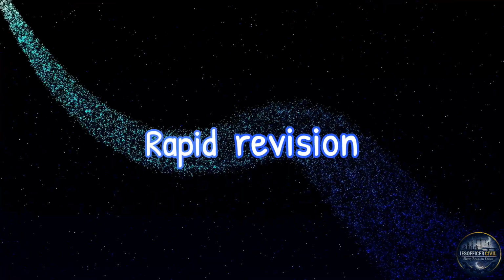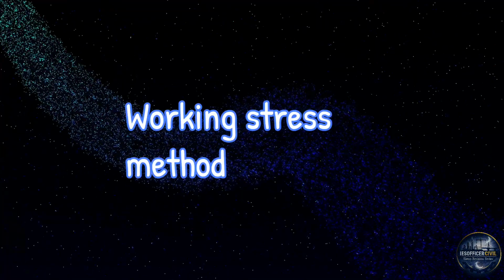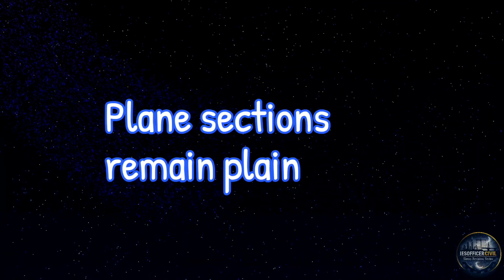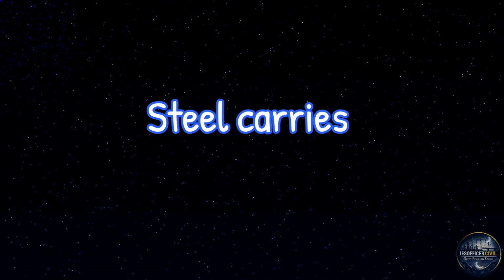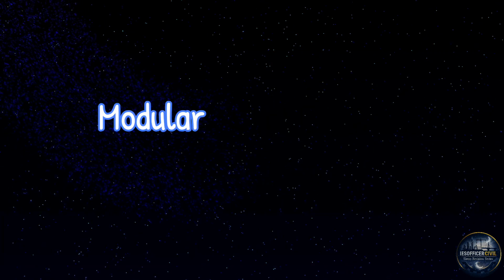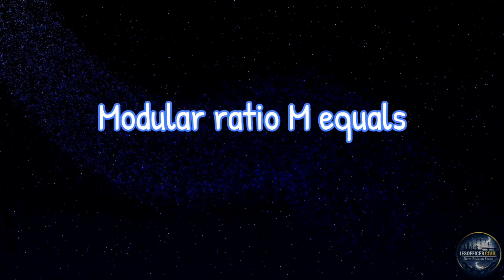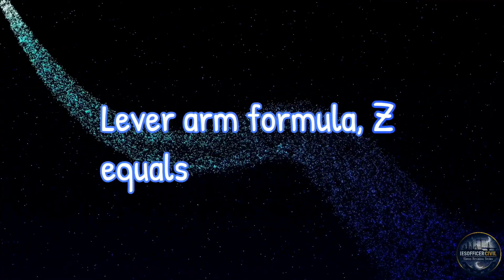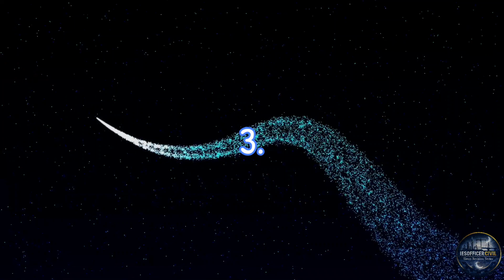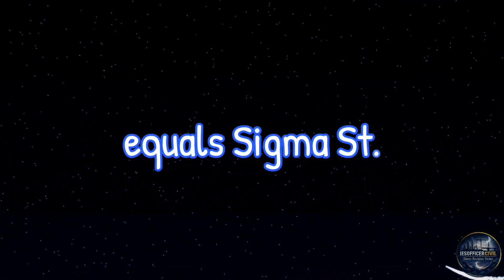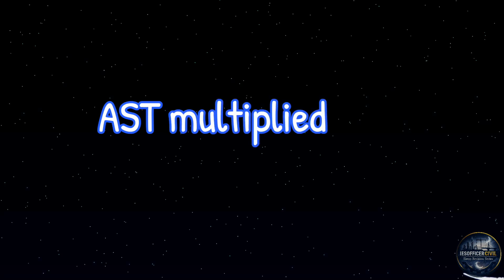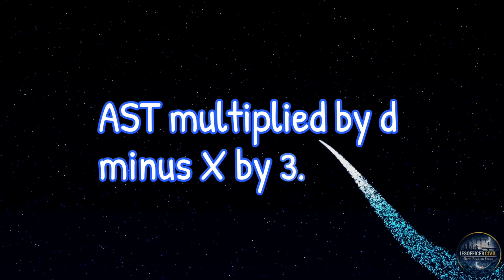Now, rapid revision. Working stress method is elastic method. Plane sections remain plane after bending. Concrete carries compression. Steel carries tension. Modular ratio m equals Es divided by Ec. Lever arm formula z equals d minus x by 3. Moment of resistance MR equals sigma st Ast multiplied by d minus x by 3.